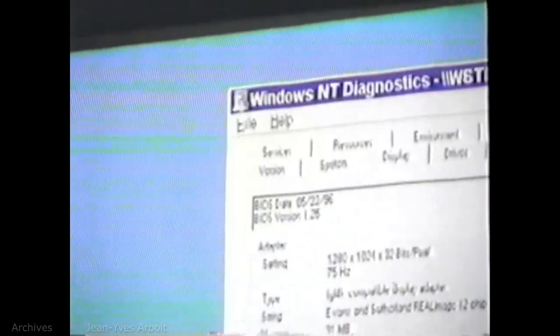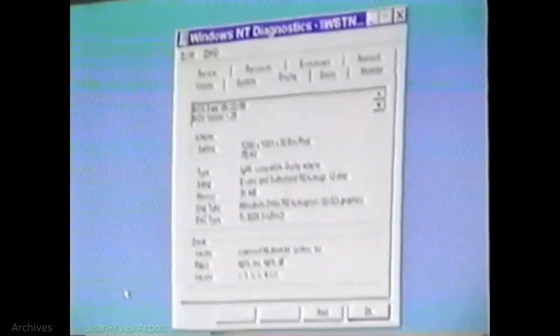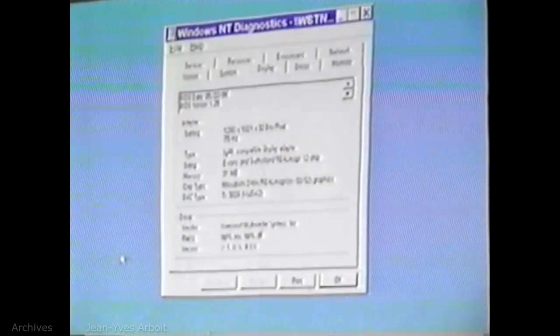How much VRAM do you typically need? How much VRAM? Typically around 16 megs as a rule of thumb. All the graphics driver manufacturers use their memory differently, so that's why I said it's a rule of thumb. 16 might be fine for an Intergraph, but it might not be enough to run at 1280 by 1024 on another driver.